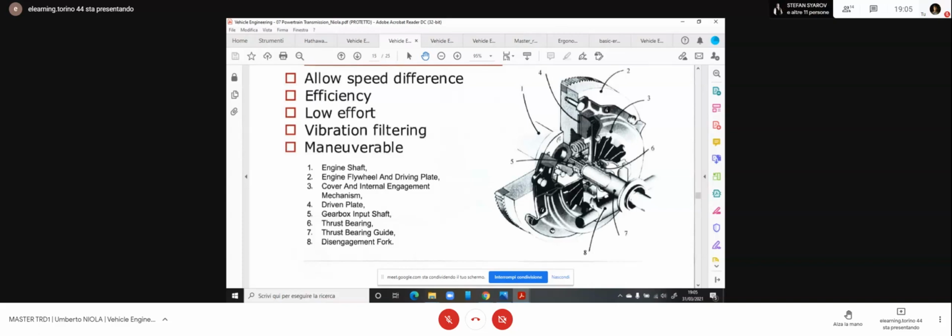This is used like a lever because it is hinged. You have a fulcrum here in this position, in this middle crown. So the pressing end of the spring is pulled out. You relieve the pressure over this pressure disc, which is squeezing the friction disc, the clutch disc, in between this external part and the flywheel.